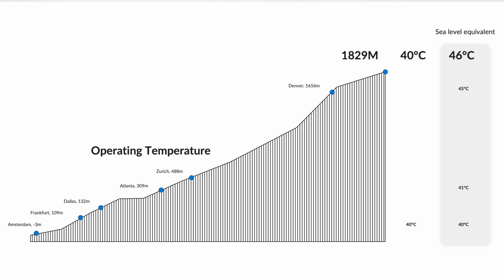Now, the second parameter that influences every single electronic component will be the elevation, and for a simple reason. The cooling capability is a function of the air pressure, and therefore the altitude. We use a simple rule of thumb to say that 1000 feet, around 300 meters, is equivalent to 1 additional degree Celsius at sea level. Consequently, to support a system at 1800 meters of altitude, you need to test it at the maximum temperature plus 6 degrees. In our recent routers, that will be 40 plus 6 equals 46 Celsius.